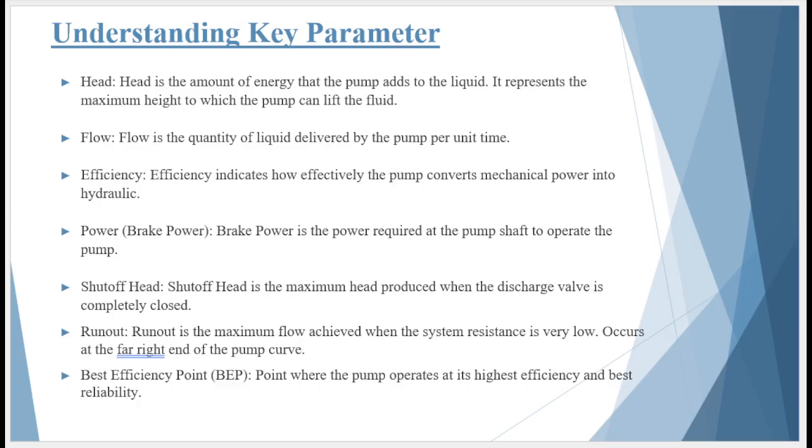Head. Let's start with head. Head is the amount of energy that the pump adds to the liquid. In simple terms, it represents the pump's ability to overcome system resistance and move the liquid from one point to another. Head is usually expressed in meters or feet. It is important to remember that head is a measure of energy, not the physical height of the pump.